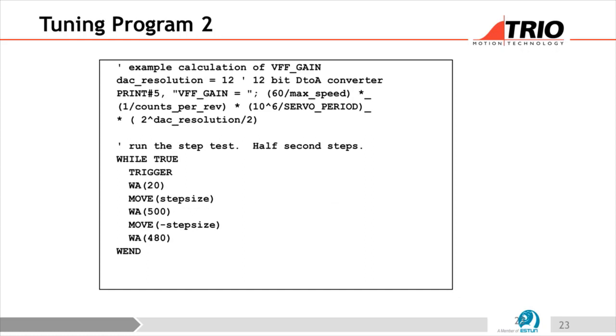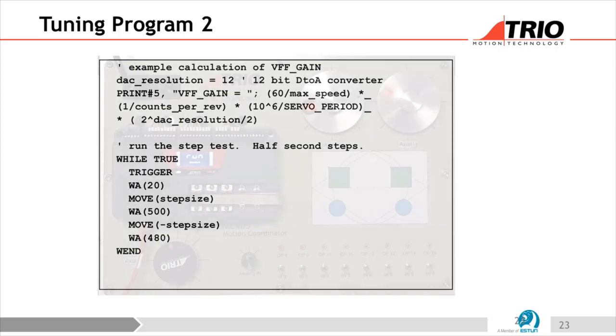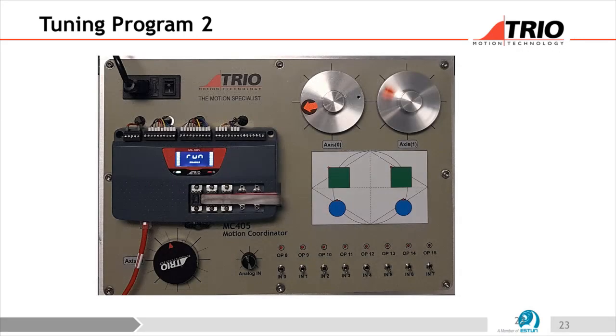Okay, so I've got one other thing that I need to say about these rigs though, which is that all this time I've been talking about the fact that the 10 volt output is proportional to speed. With these rigs, the little motors on them don't have a speed control. So the little drive is just giving the motor a current, so effectively controlling the torque on the motor, not the speed on the motor.